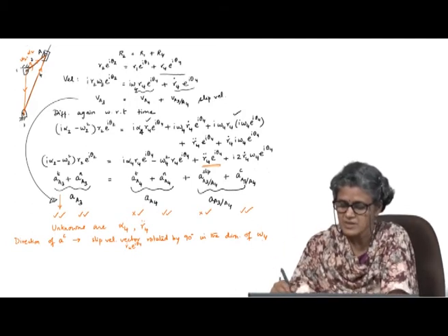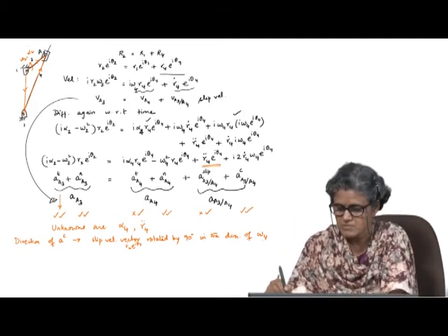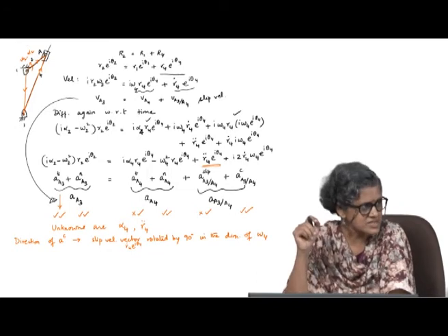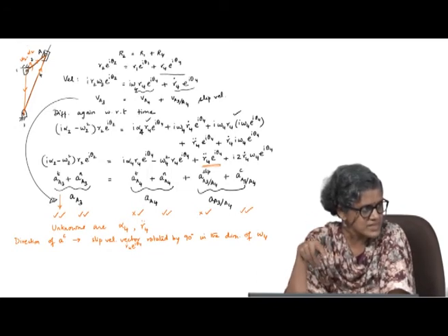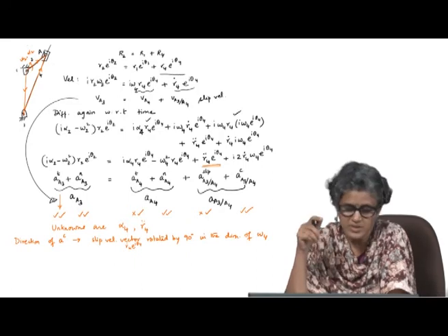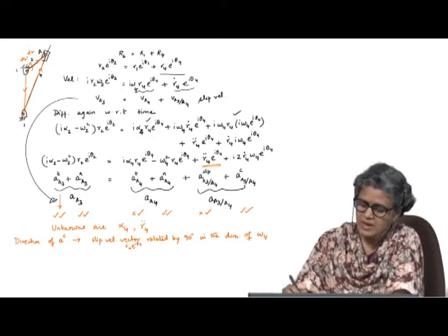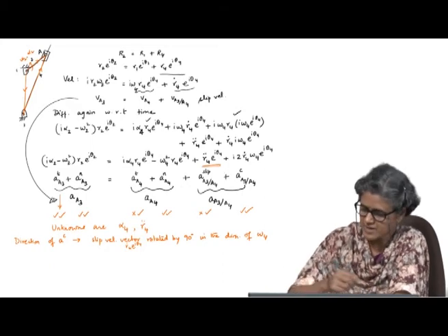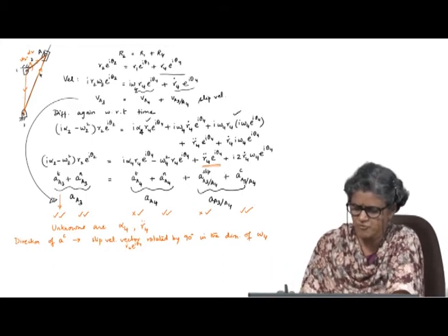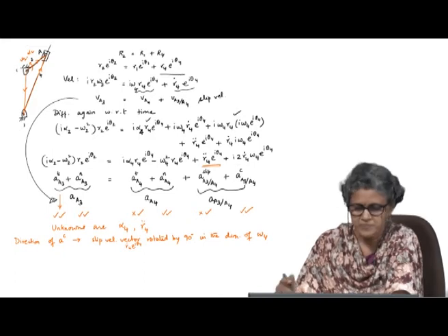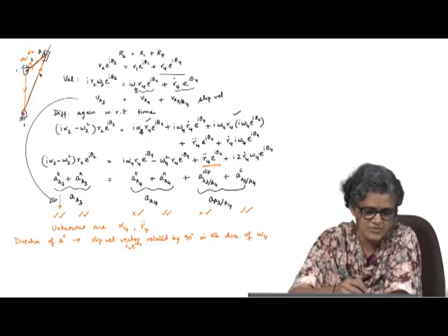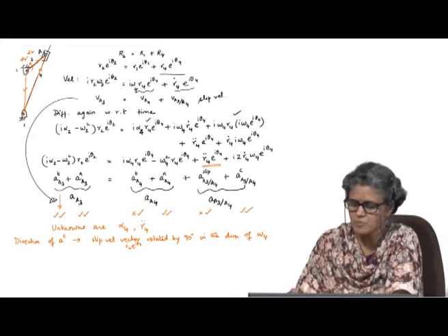So, plotting that in the graphical analysis requires some attention when you are doing it. And this will be along the vector. So, it is sort of the same form. This would actually be perpendicular to this link. The Coriolis acceleration will also, so these are 2 perpendicular components.